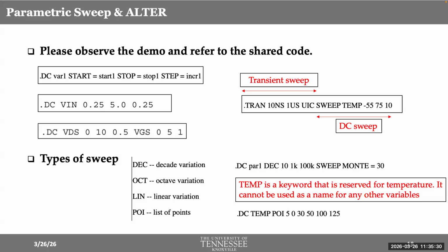And it becomes extremely powerful when you use alter. Remember I told you about alter? You can just keep altering the conditions of the simulation as many times as you want. There is no limit. And that way, this becomes very powerful when you want the computer to work while you're not in front of it. So just submit a really big set of commands with multiple alters, and when you get back, you see a lot of results. The more you automate, the more optimization is possible.